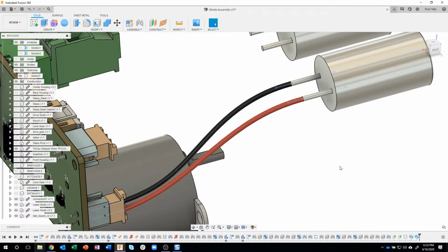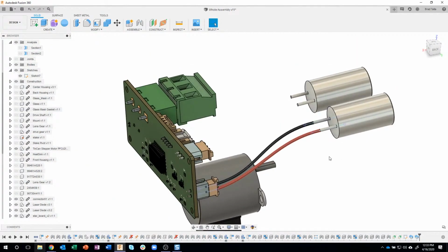Okay, so that's the basics behind creating wires. We start with basically a 2-point spline, and then we control the tangency anchor to a certain direction, so we want it to go off of a certain wire and into another, like a connector, for example. What we're going to do next is a ribbon type cable. I'll show you some cool stuff with this.